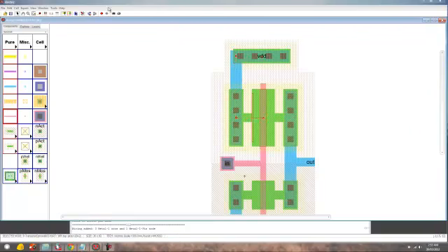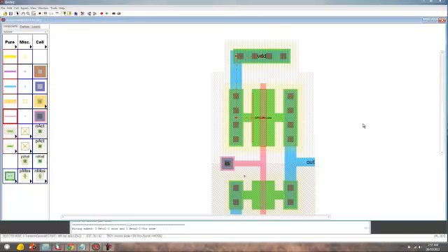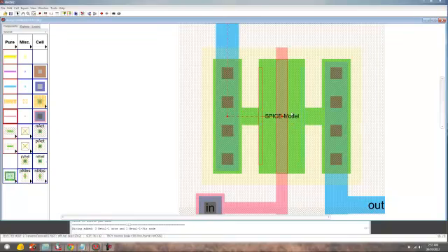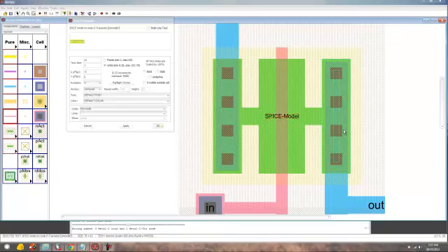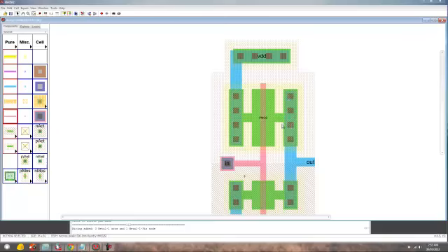Okay, now we have to set the SPICE model. Click on the VDD, make sure the connections are connected by the red dotted line. Select Tools, Simulation Spice and Set Spice Model. There you see the text. Press Shift or Control and click on the text, Control I and change it to PMOS. Here goes.